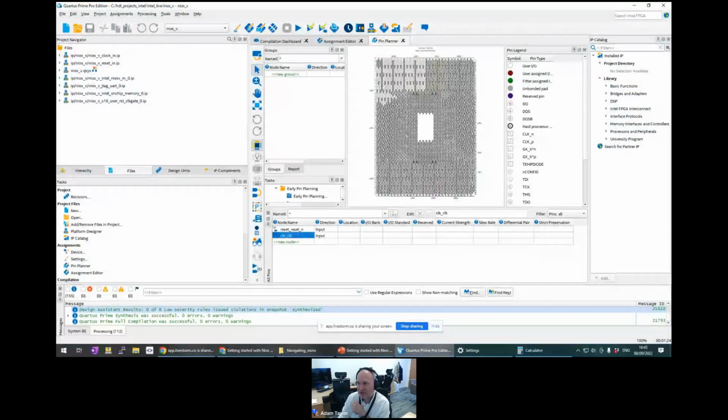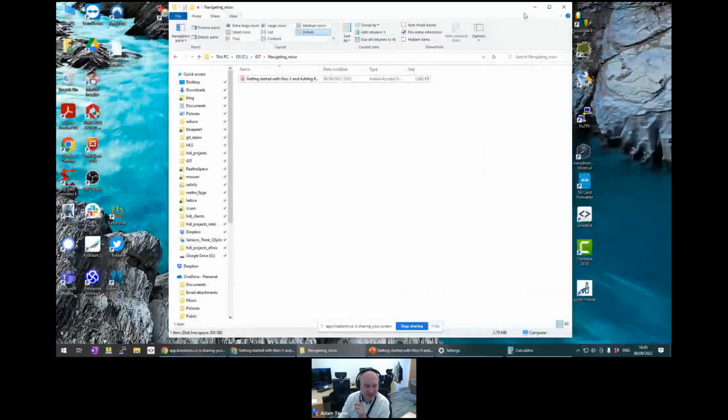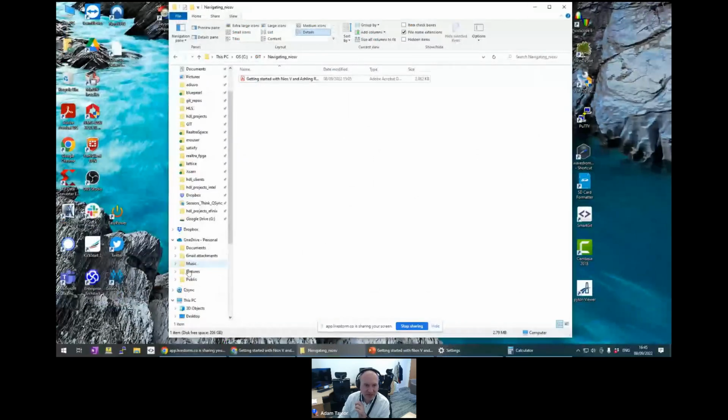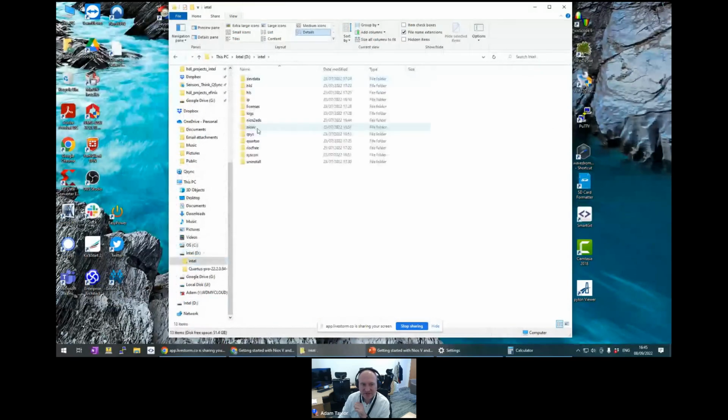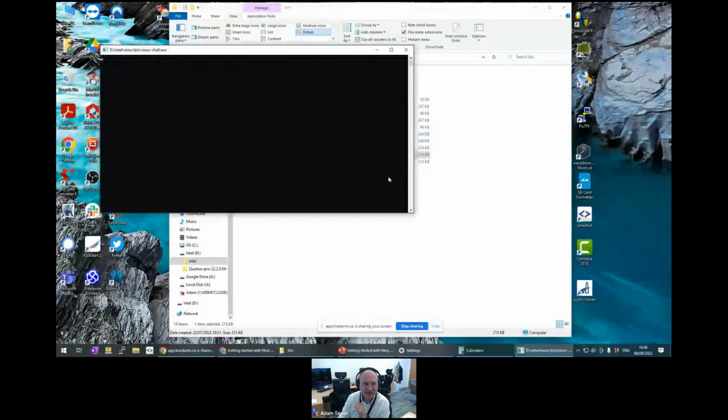Now, because I'm going to use the pre-existing design for this, because we don't have time to build that, I'm just going to go to my installation directory. I'm going to find the Nios V, find the thing called bin, and run the Nios V shell.